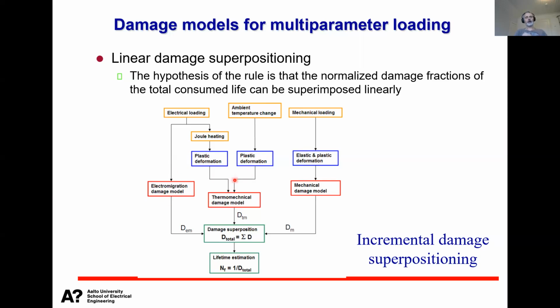This approach assumes that the structure is constant, and it withstands a certain amount of damage, and then it fails. So you have a starting value, then the damage value, and different stresses increase your damage, and when you reach the maximum damage, it fails. You are summing up the damages, but the interaction between the stresses is excluded in these models.